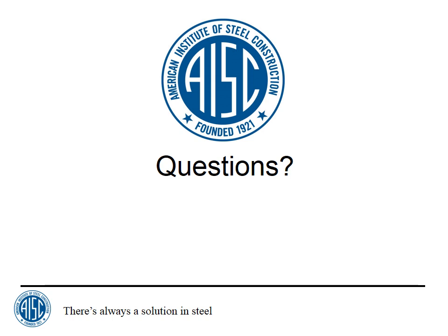But yeah, I would treat prying action in that case. And in this forthcoming design guide by Larry Muir and myself, there's an example that does exactly that. If it's to a column flange. If you're talking about a column web, then there wouldn't be any normal force to the web, so you wouldn't have any prying at all in that case.